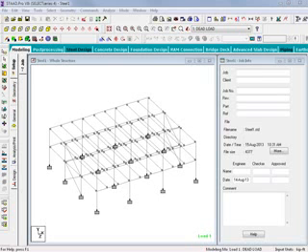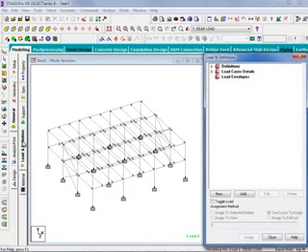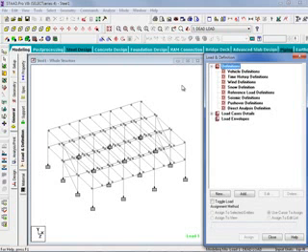The first step for incorporating our wind load definitions is to select the General tab in the page control area, followed by the Load and Definition subtab. In the Load and Definition dialog, we will expand the Definitions group, and we will see that load definitions can be used for several different loading types to add more information to the model.